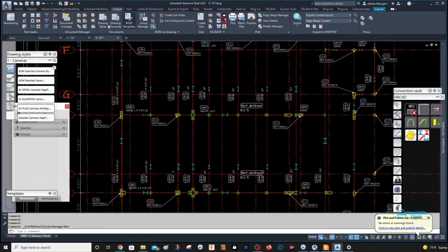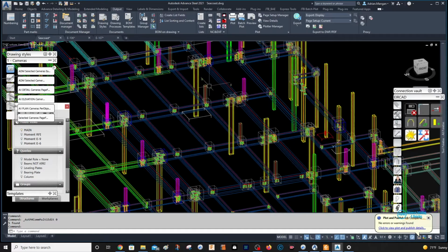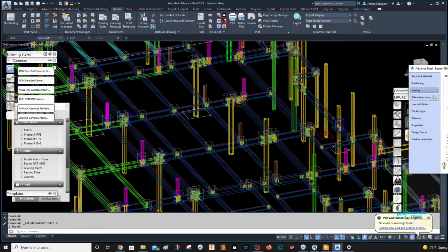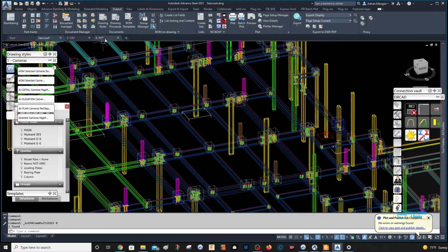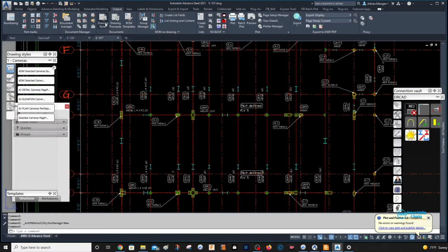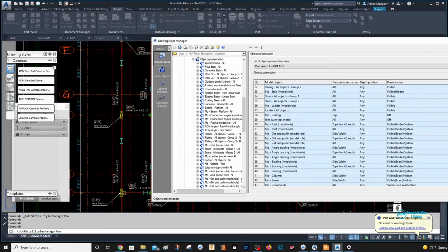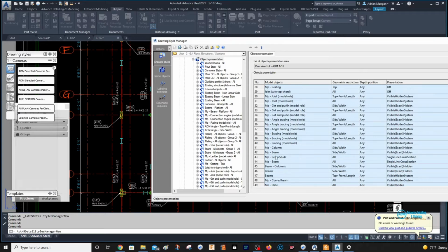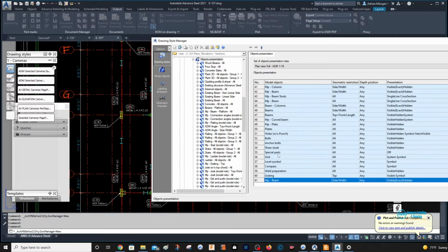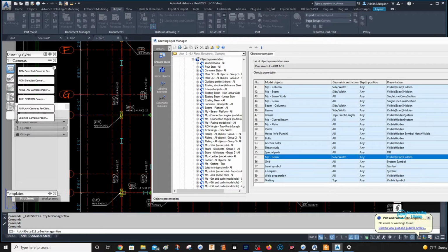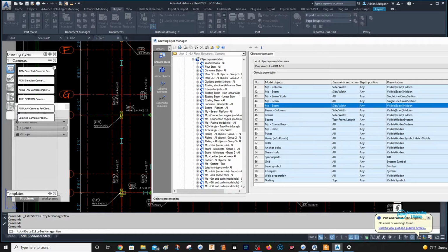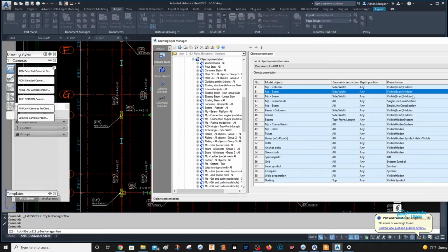If you can see, let's go back to the drawing and see what I have it in as. Oh, sorry, I obviously don't have it in as column because it's in as wood, so it's going to be regarded as a beam. So we'll open this again, and go to that beam side width, and just create a new one. And I'll come down here, and because I usually forget to do it afterwards, I'll move this up above the other one.